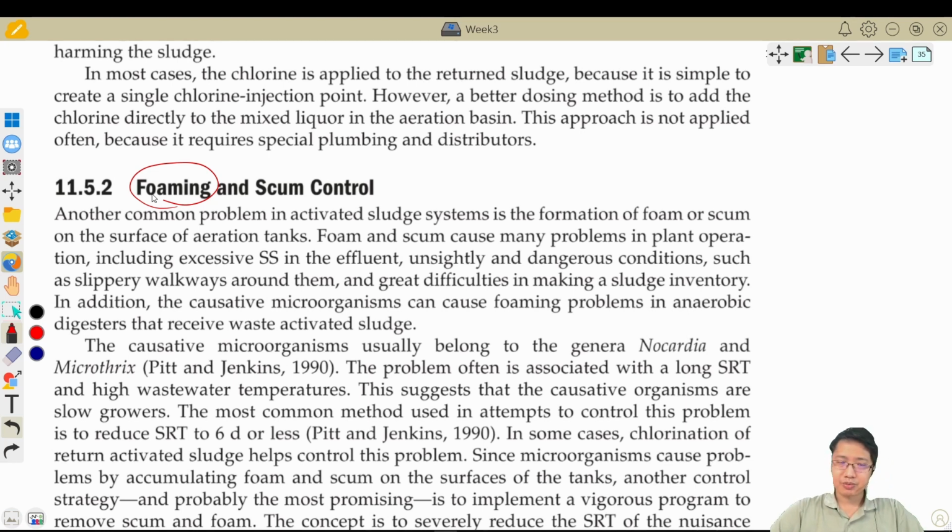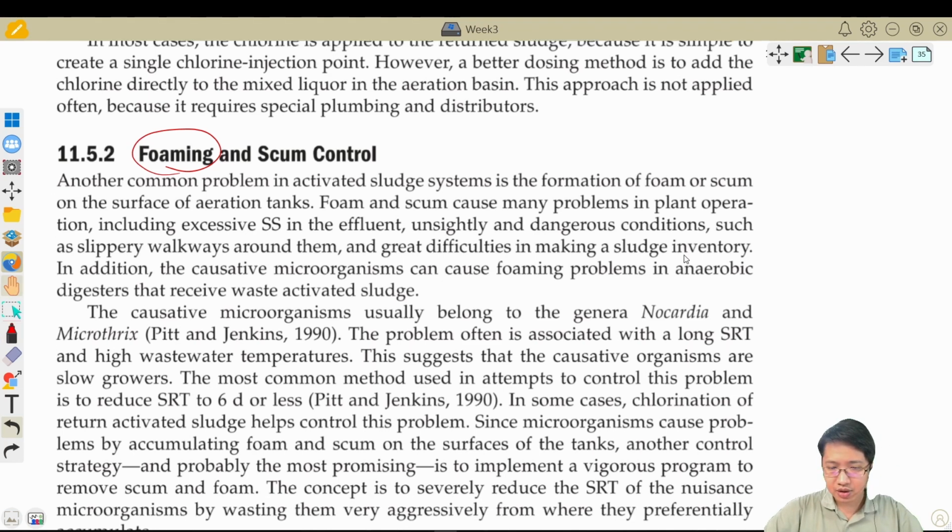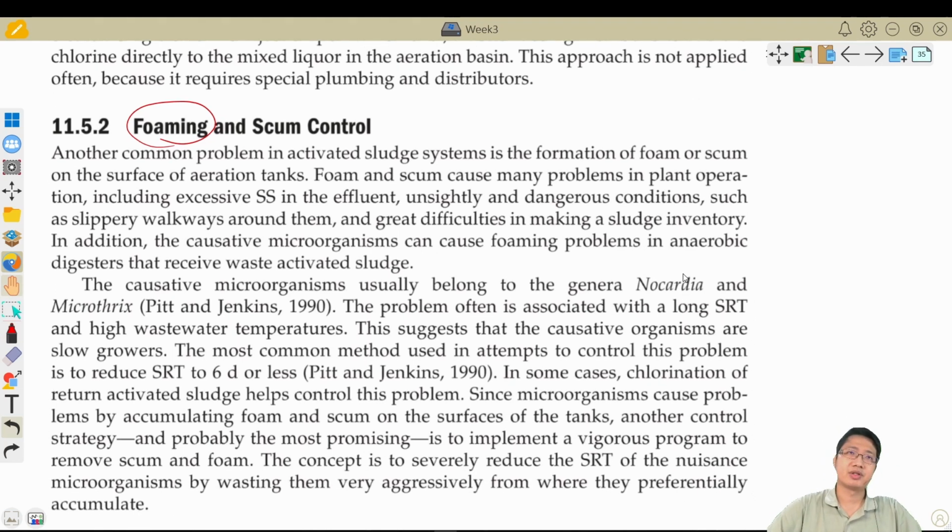After the aeration, those bubbles will flow up to the top of the reactors and cause your sludge to be attached to those bubbles. So under these conditions, you won't get very good settling capacities in your settling tank.